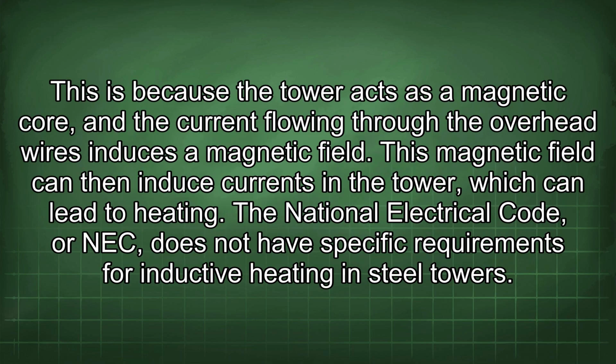This is because the tower acts as a magnetic core, and the current flowing through the overhead wires induces a magnetic field. This magnetic field can then induce currents in the tower, which can lead to heating. The National Electrical Code, or NEC, does not have specific requirements for inductive heating in steel towers.